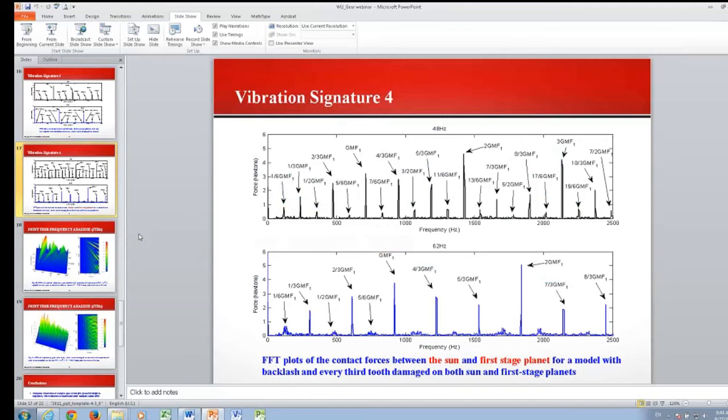Okay, so this is the difference between atoms and FEA. For the atoms, you will calculate the stress and the strain. In this way, you can predict the life of the gearing system. But in my study, I'm the system engineer. That means in our study, we focus on the whole system's dynamics behavior. So temporarily, we let another group of engineers do the FEA analysis. We call that a local analysis. In this way, you will look at if there's a crack, how it propagates.